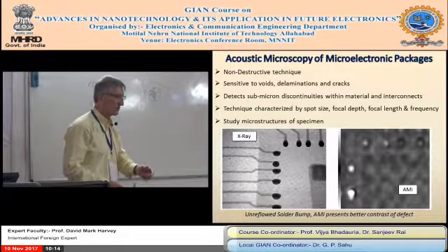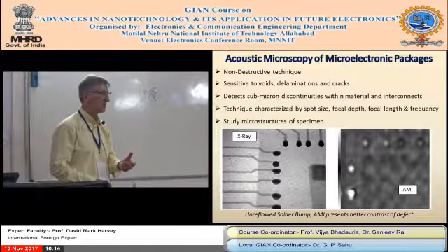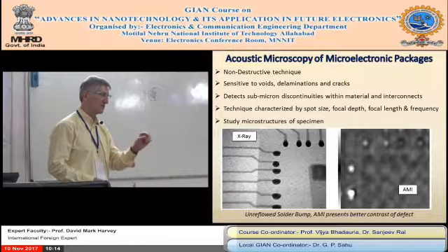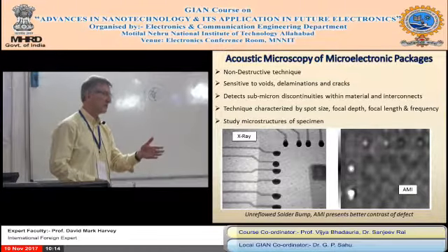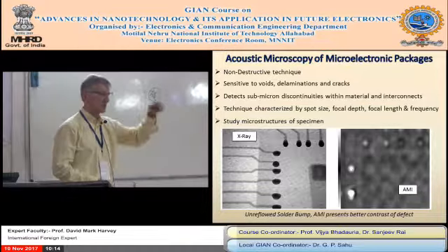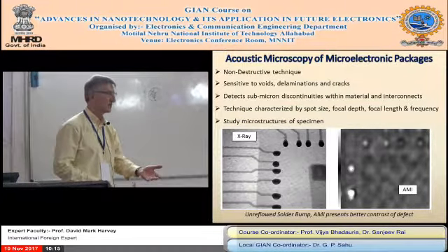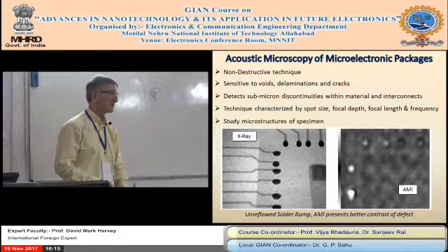The higher the frequency, we go up to about 1 gigahertz now, but on our equipment we can go up to 400 megahertz. The higher the frequency, the better the resolution, but you don't get something for nothing, the lower the penetration. So if you've got high frequency, you can't penetrate through the product. Whereas you go down to, say, 10 megahertz, you can penetrate through the product a lot deeper, but you can't get the resolution. So there's a solution for you.